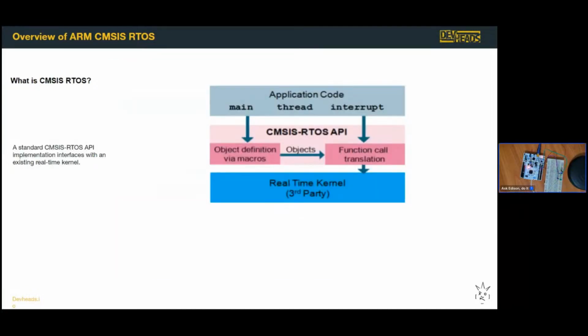So what is CMSIS-RTOS on its own? It is a standard CMSIS-RTOS API implementation interface with an existing real-time kernel. So, like I said, you have to, the CMSIS-RTOS sits on another RTOS.